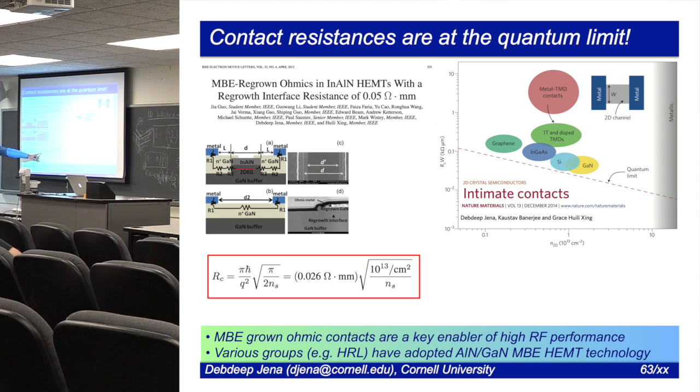And this used to be a very small resistance, maybe about 8-10 years ago. But now the channel is so small that there's no resistance in a transistor. I mean, it's already like 10 nanometers now. So there is no resistance in the channel. All the resistance is this. And you have hit some sort of a limit, because you can't go below this if you have a perfect crystalline ordered material. At least that's what the theory seems to be saying, that this is your minimum of resistance. And this is dominating the resistive loss now in the device, because this channel is already so small, right? So it's a very important thing.